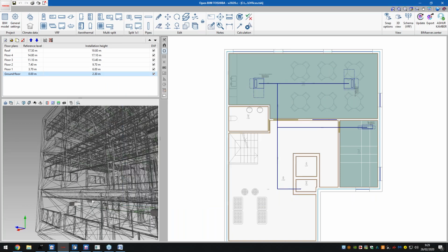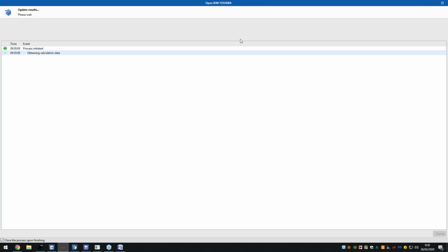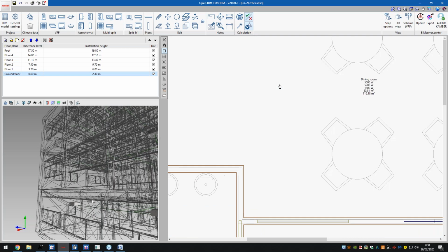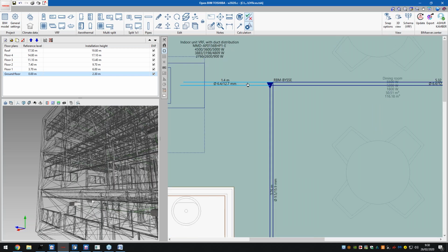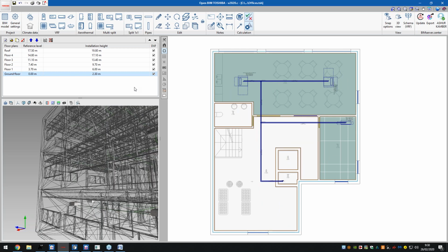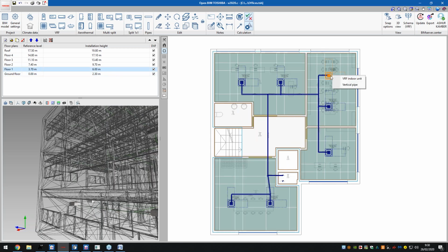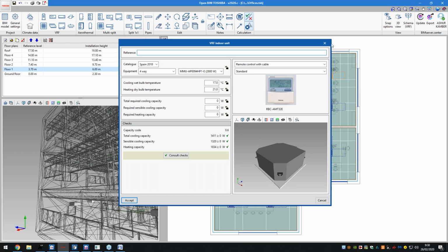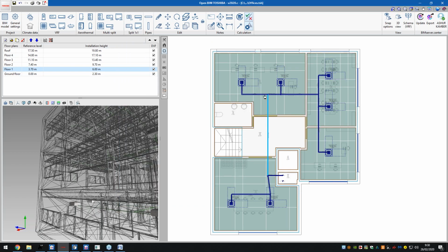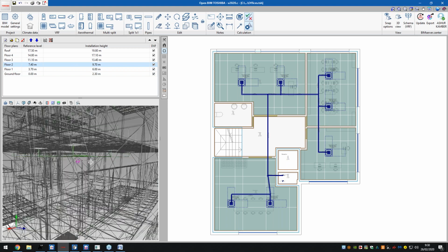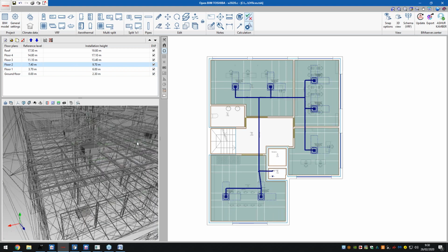Now, not only can we intelligently select certain models, but we can design our installations. Now, upon selecting design, we get our pipe diameters, our pipe lengths, all within the program and defined internally here. And you can see as well, I'm able to view those and view the checks for those particular elements as well. So quite nifty in this certain workflow here. And you can see as well all my installations within the 3D model.